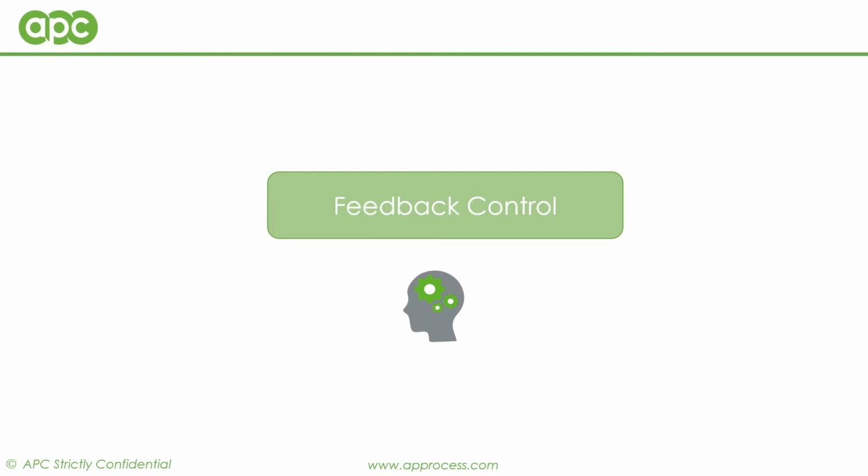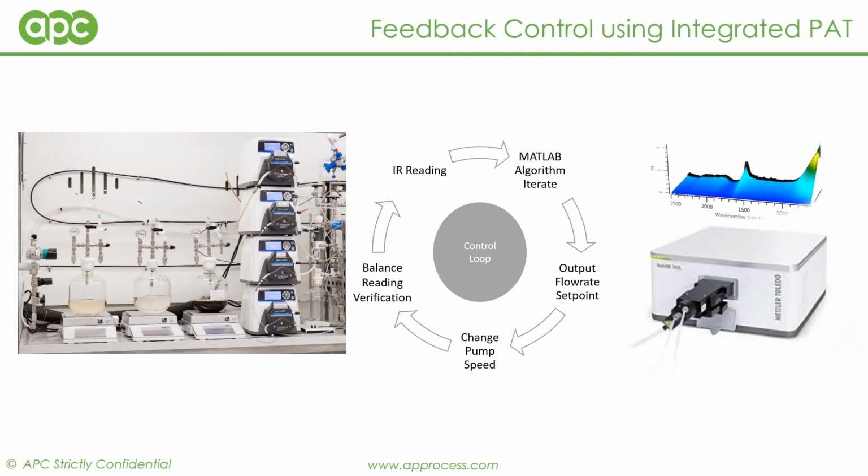Although feedback control loops are important for batch operations, they're inherently less risky, as all of these steps are not telescoped together, and the material is generally separated and tested prior to feeding the next step. The first step in building a feedback control loop is identifying a suitable way of quantifying the parameter of interest, the parameter which the feedback control loop will use to control the process.